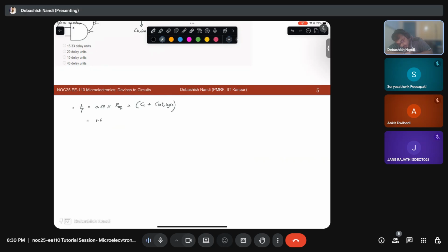So I'll have 0.69 times R equivalent times C internal logic times (1 plus CL divided by C internal logic). Fine.